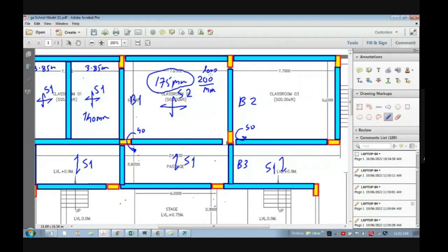Don't worry, 200 is comparatively very less depth. Okay. But are there some other methods, sir, to reduce the depth of the slab? See, reducing the depth of the slab is not really possible because most of the time, yeah, people do post-tensioning methods. Yes, sir. They do post-tensioning, but still there is a limitation. You cannot reduce so much depth because shear force comes, and then you need to provide drop panels and so on. So whenever you take any decision, there is an implication.